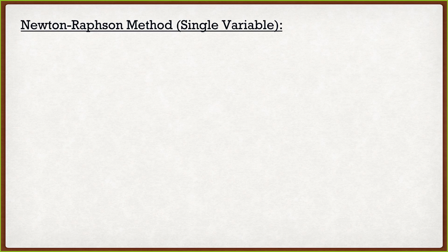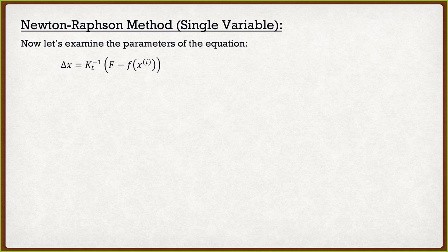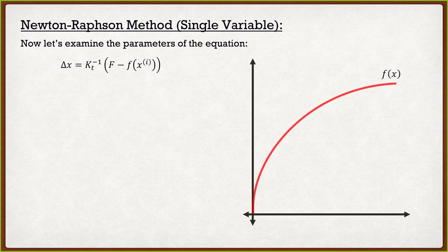So now we're going to examine the parameters of this equation that we just derived, but in the context of some meaning. So let's say that I have a curve right here. Let's say that this is a stress-strain curve, and our stress-strain function is defined by f of x. That big F there, that's the value we want. So if I'm loading this, I want to load it up to a certain value. I say I want to load it up to the value F. The question is, how do I get to that value F?